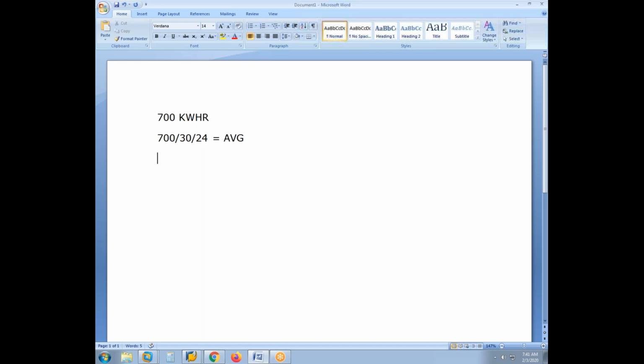Say, for example, we have a bulb of 100 watts running for 10 hours. So consumption is going to be 1000 watt hours, which is 1 kilowatt hour. And 10 rupees is the price, so it is going to be 10 rupees. But we also have a bulb of 1000 watts running for 1 hour. Here also consumption is 1000 watt hours, and it's going to be 1 kilowatt hour.